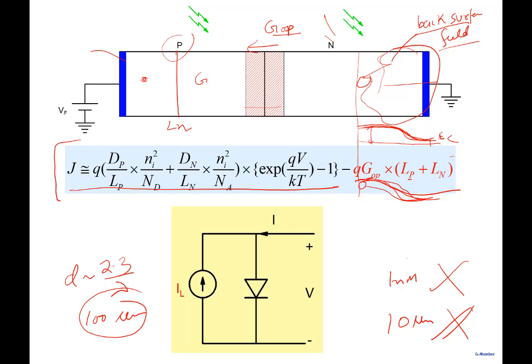And why do holes want to come here? Because you have created depletion edges there, so holes may want to come here, diffuse and get collected. This is like a sink here, right? So you have to do these things in order to prevent the hole from going towards the opposite side. You want the holes to go towards the left here, right? But you can only collect everything within the diffusion length of the holes.